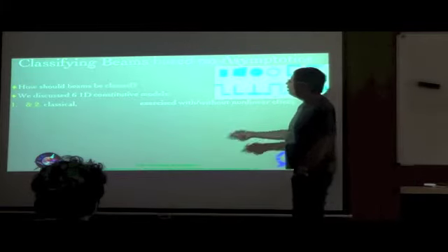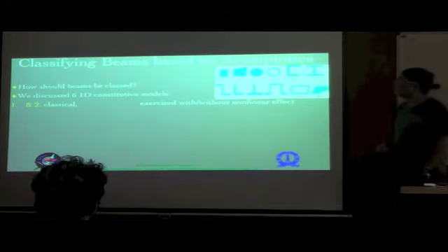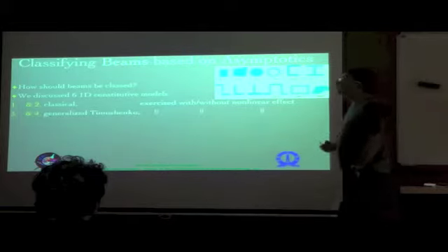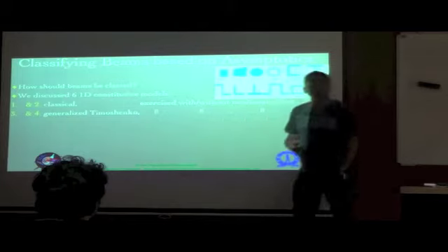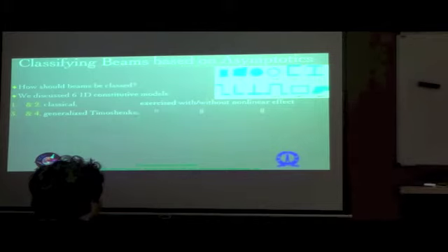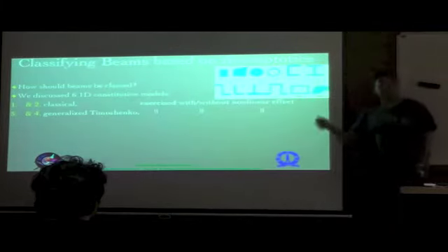The first and the second models are the classical model, which is the 4x4 model, with and without the nonlinear effects, that is the cubic terms that we discussed in the previous slides and the slides before that as well. The third and fourth constitutive models are the generalized Timoshenko models, where you will explicitly bring in gamma 1,2 and gamma 1,3, which are the transverse shear 1D strain measures, in addition to the 4 that you already have, namely gamma 1, kappa 1, kappa 2 and kappa 3. So you have a 6x6 matrix, again with and without the nonlinear effects depending upon a particular cross-section geometry.